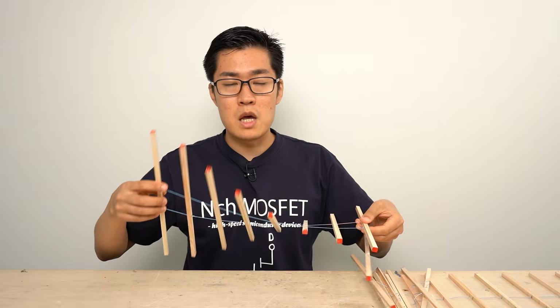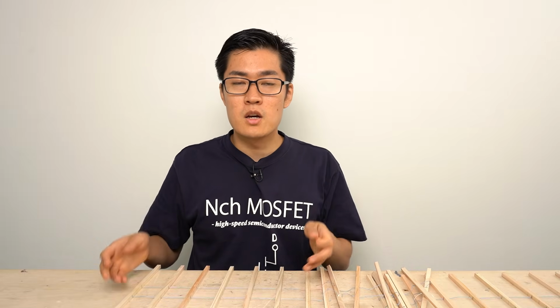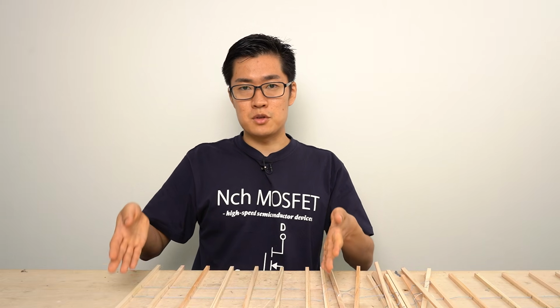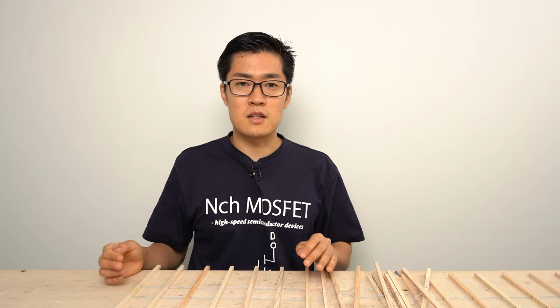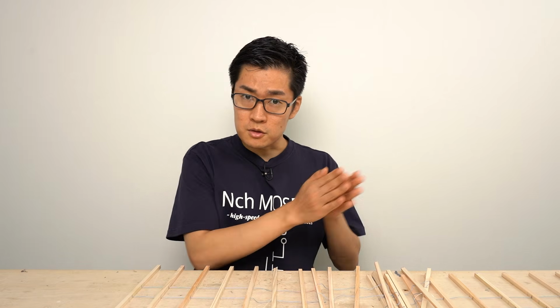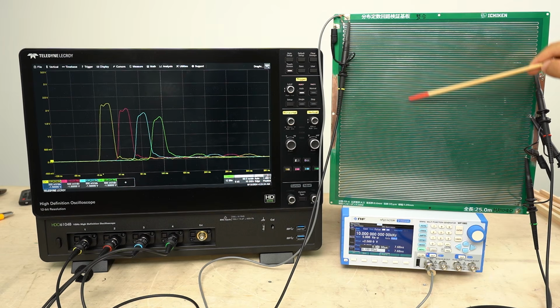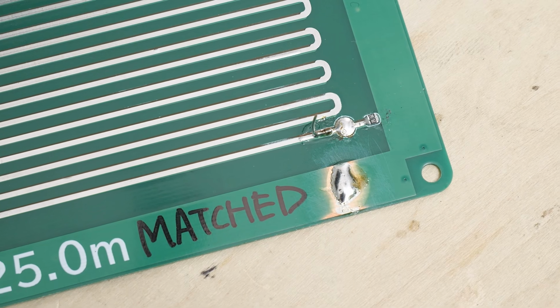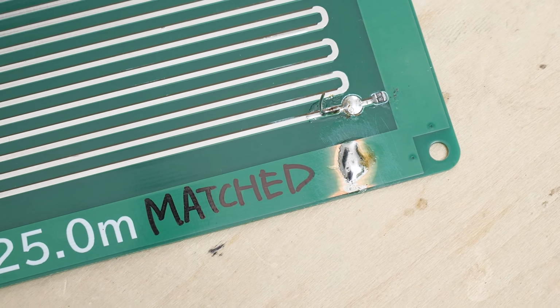So what does it mean for a wave machine to have impedance matching? It means that if you set up another wave machine with the same characteristics and connect it, impedance matching is achieved at the connection point. The waves will keep traveling without reflecting at the connection point. I designed this electric circuit to have a characteristic impedance of 50 ohms. If you put a 50 ohm resistor at the end, the waveform won't reflect at all.